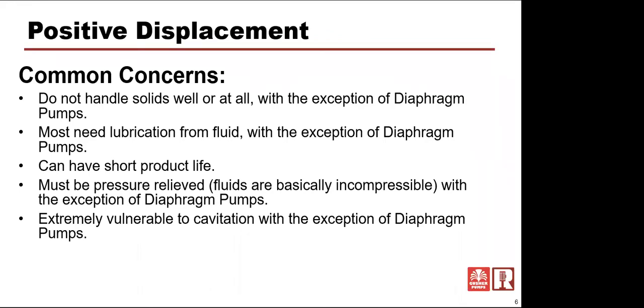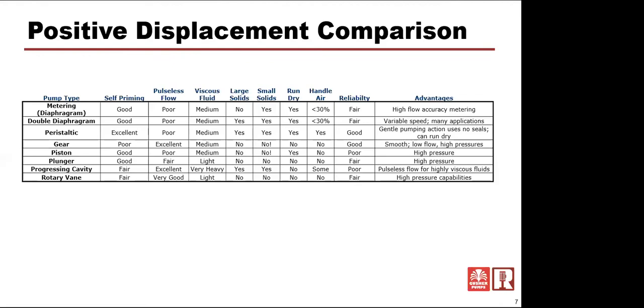Of course, toothpaste is very thick, very high viscosity, and difficult to pump. Again, they must be pressure relieved. That's absolutely critical. Some pumps have the pressure relief valve in them. Positive displacement pumps have a pressure relief built into them. They are extremely vulnerable to cavitation because of those close tolerances and the pressures that they build. We'll talk a lot more about cavitation as we go forward. Again, this is just kind of a quick overview of positive displacement pumps.